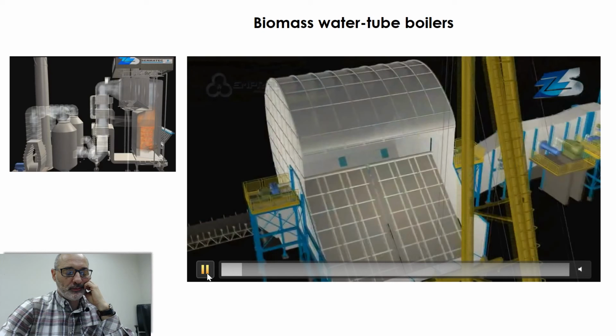This is just the diffuser's chain cleaning system. Don't bother with that. This is bagasse. First dewatering mill, second dewatering mill. Here you have bagasse at 50% humidity, which is injected into the boiler here. It's being injected inside. It's going to show you inside in a moment. The combustion takes place here. The preheaters and so on.